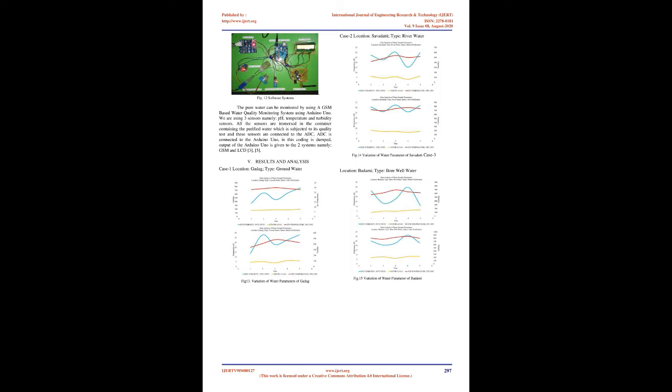Fig 3c shows the cotton layer. By passing the water through an effective filter, most cholera bacteria and other pathogens are removed. It traps any physical debris present in the water. Fig 3d shows the fine sand layer. It is used for removal of suspended matter, as well as floating and sinkable particles. It purifies the insoluble particles present in the muddy water.